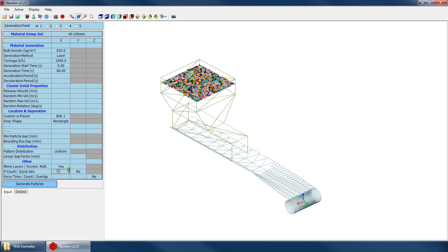But if you want, you could say, nope, I want you to generate 100,000 particles before you start copying layers. Then as I generate, this is going to take much, much longer, because now you can see it generated 100,000 random clusters. So then it'll get to the end of that, and it'll only generate an additional 10,000 clusters. It'll start over and copy them.